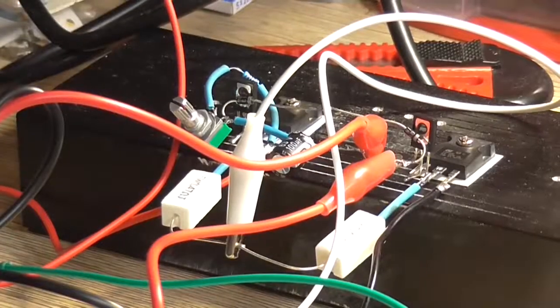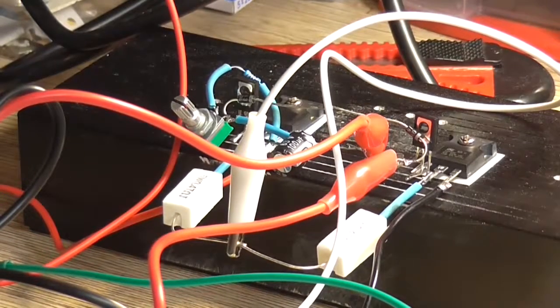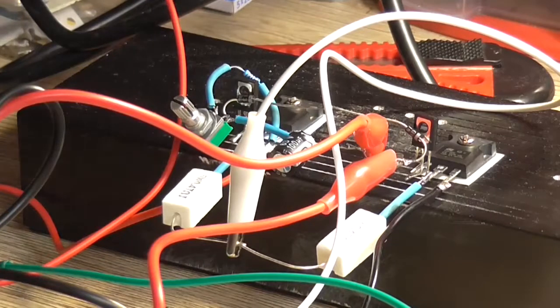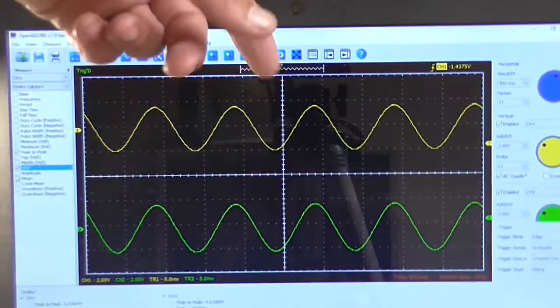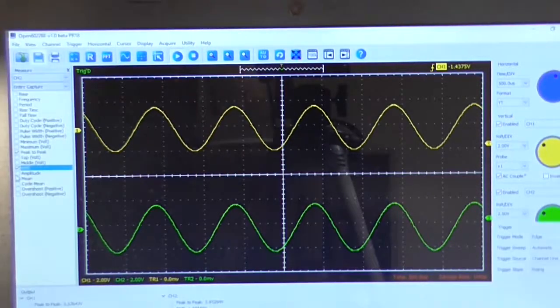So what does this mean? Not much, not diddly squat. It just means the output stage is not going to produce any voltage gain. It's not supposed to. All it does is change a smaller current flow into a larger current flow, because to have a voltage of say 4 volt peak to peak coming out of the output stage, it needs a little bit more current to drive a speaker driver than it would just driving a dummy load like this.